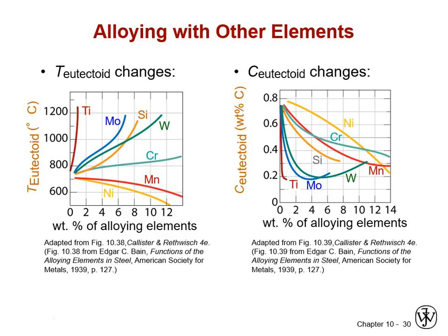And if you go into alloy development, or you're selecting a particular steel alloy, or you're working with a heat treater or a metal supplier, you'll keep these kinds of changes in mind when you think in terms of things like cost of processing and eventual properties, because the placement of these reactions on the phase diagram have big implications in processing ease and cost to whoever you're working with, which will of course be passed on to you.